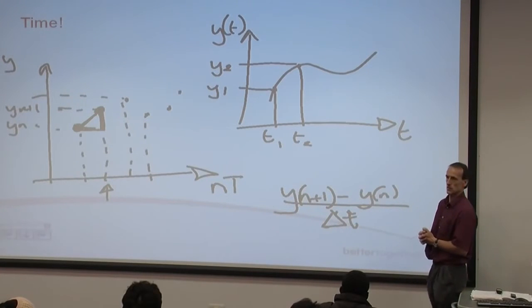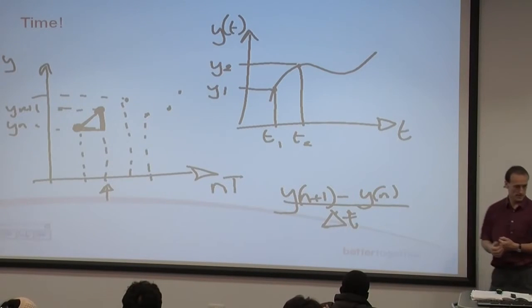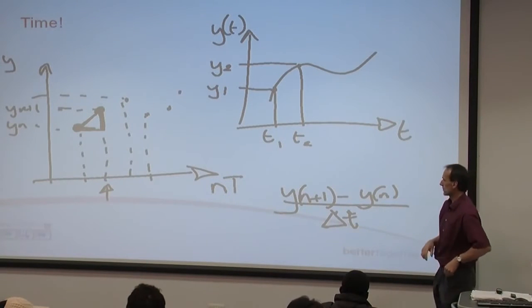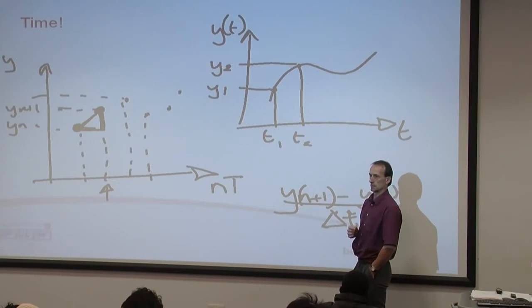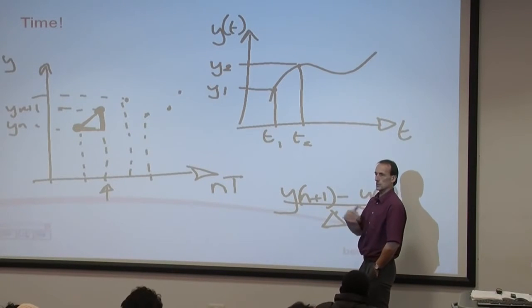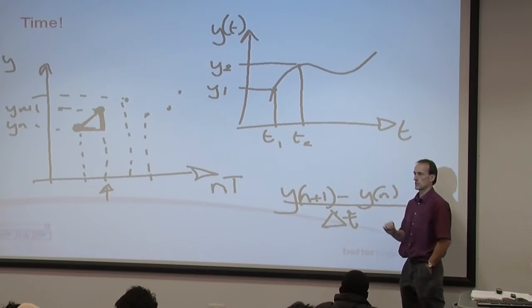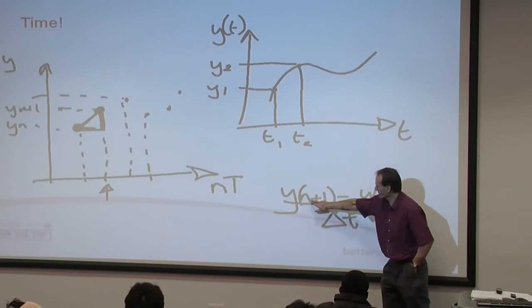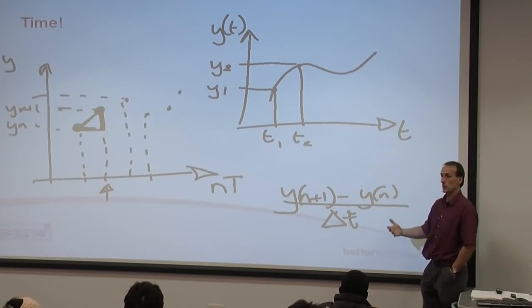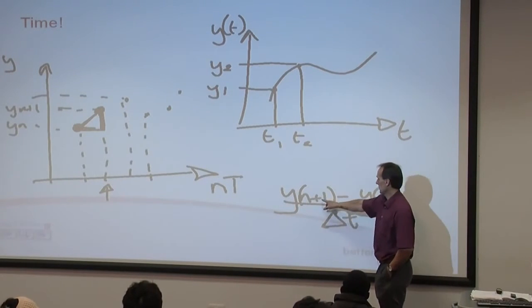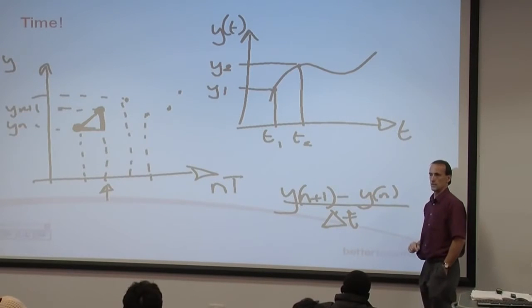And what we introduce is called the Z operator, where the Z operator represents a delay of one sample period. So we can build up difference equations, and instead of having a notation n plus 1, n, all this kind of stuff, we could use an operator Z that represents a difference of one sample period.